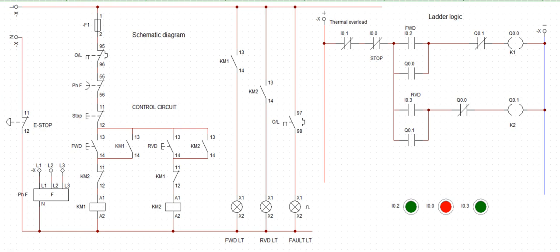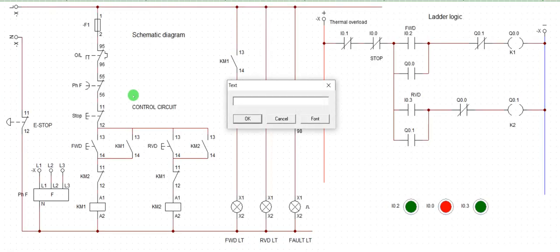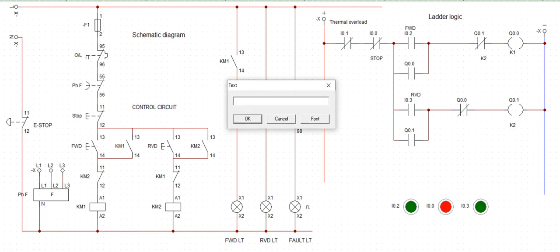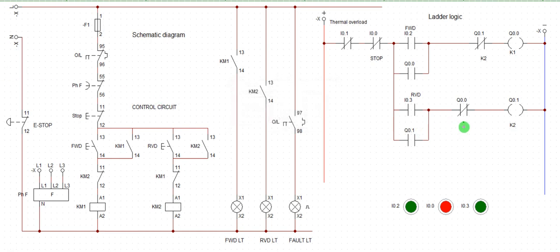Okay, we can as well add K1 there. It's going to be K2. Sorry, for the interlock, this is K2. Then this is going to be K1. This is going to be K1 to interlock the two, so they do not close simultaneously. All right. Now this is my stop button, and this stop button, start button, start button.